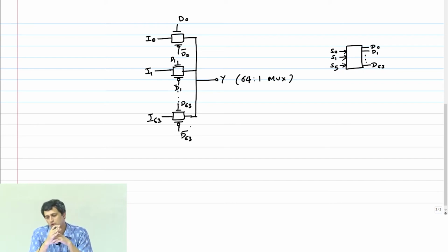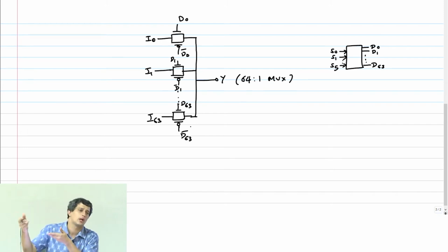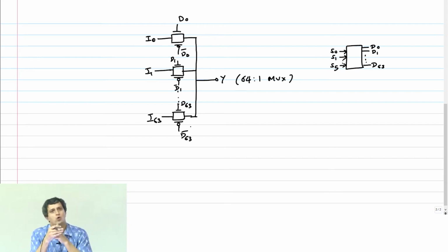So, like I told you, this is a case where both true and complement outputs are needed from the decoder. So typically here, if you want to do a decoding and then a level translation, then CVSL is a natural choice because it also does level translation for you. Additionally, it also gives you the true and complement outputs that your multiplexer needs eventually.